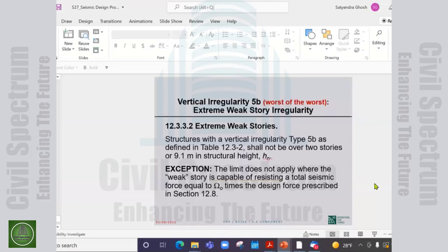The answer is it's entirely up to you. So you can do your drift computation using the approximate period. There is absolutely nothing wrong with it, or any restriction on that. You can do your drift computation under rationally computed period T with the limit C sub u T sub a, or for drift computation only, not for force computation.